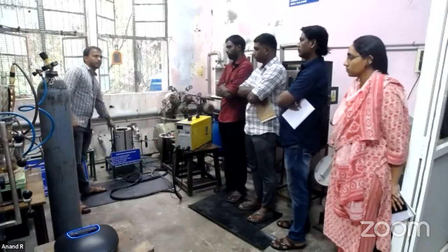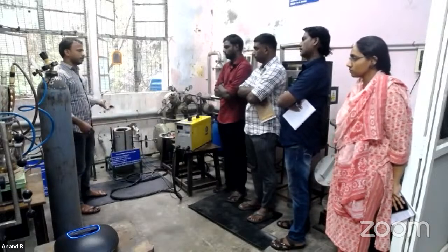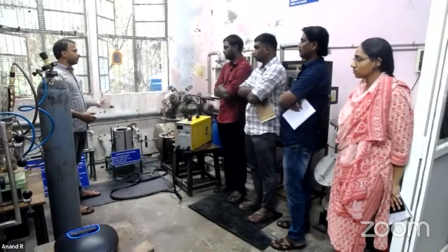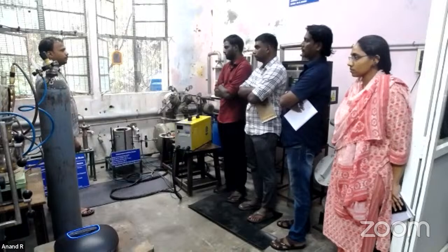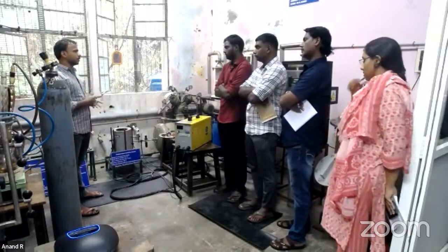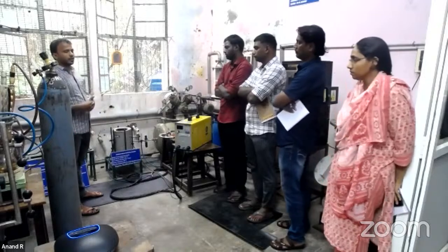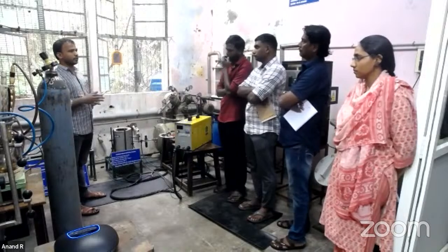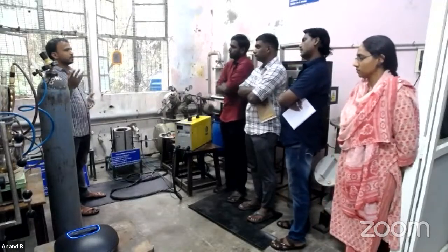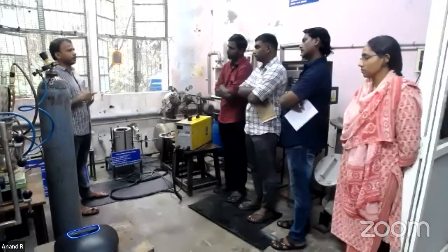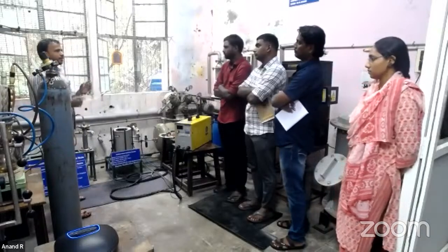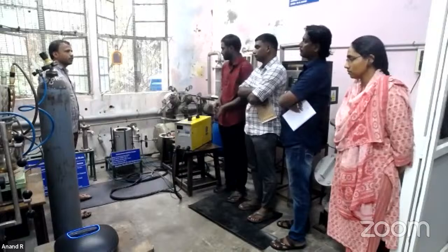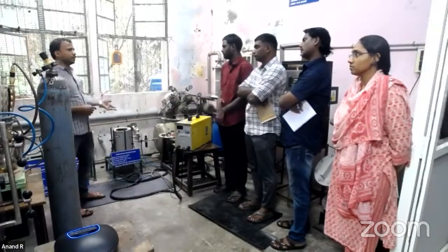If I operate the universal reactor in combustion mode or gasification mode: in combustion mode, you can supply sufficient air, and then clean flue gas will come. That clean flue gas contains only CO2; other than CO2, everything is eliminated. In global warming potential terms, CO2 is equivalent to 1 kg CO2 equivalent. But CO means 5, CH4 means 25, NO means 240. Similarly, those multiples will come, and based on that we decide global warming potential. It does not have a unit; we use CO2 equivalent as the unit. So if only CO2 is emitted, it does not highly affect global warming.